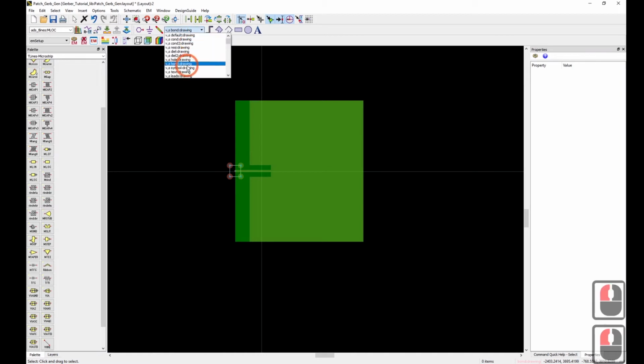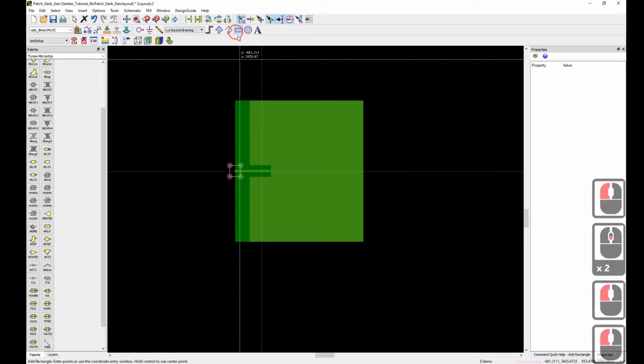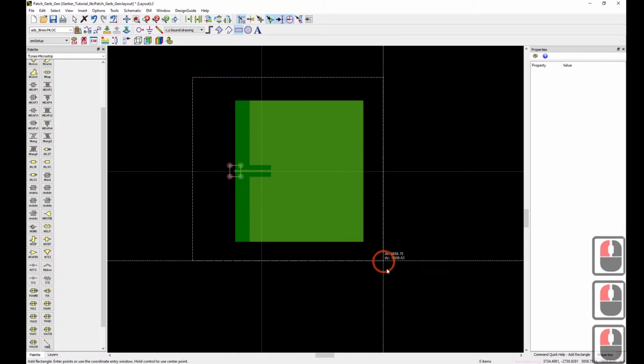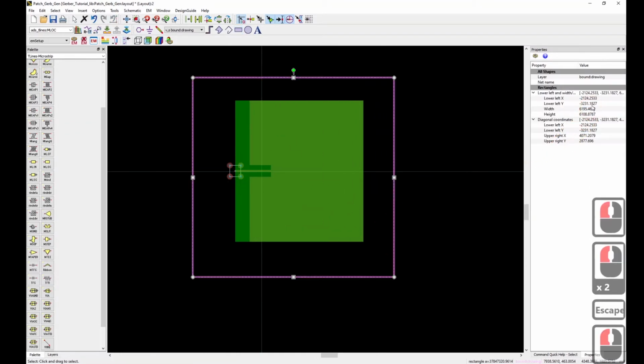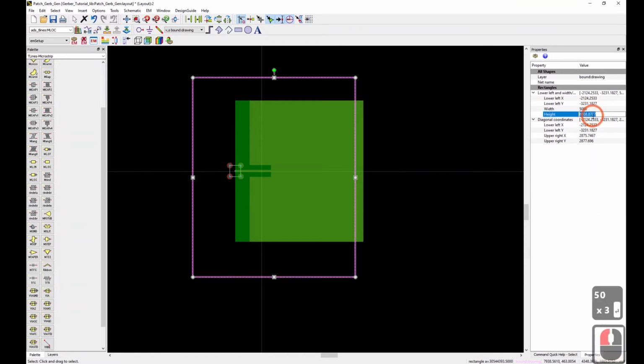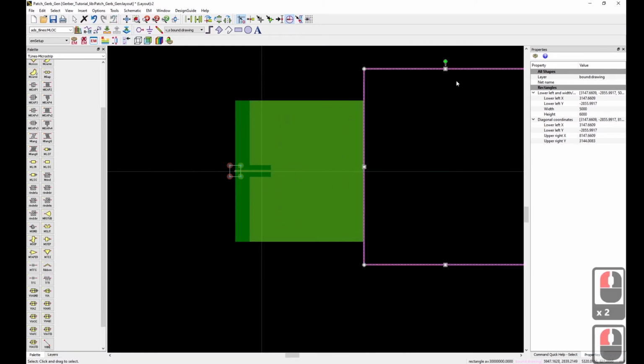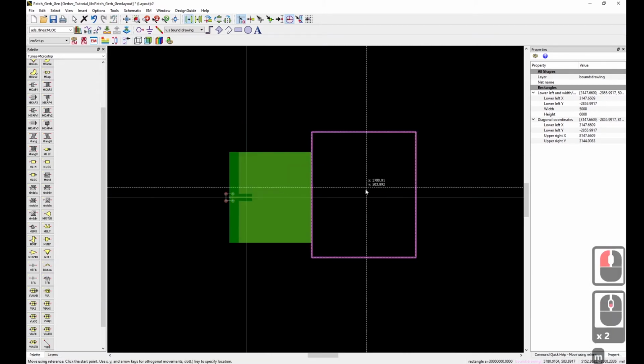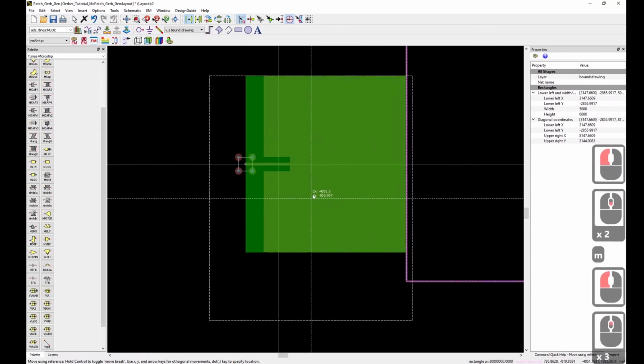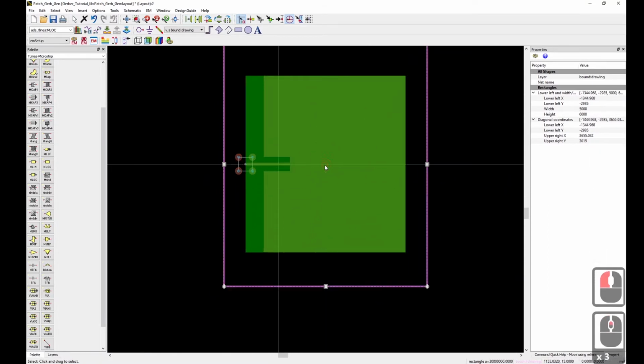So let's create bound. Oops, that's bond. Bound. Let's create a new square here. Let's make it 5 inches, which is 5,000 mil, by 6 inches, 6,000 mil. And let's just turn on center snap mode. Might even be easier if we move this over here for a second. Let's let it find the center. And then over here do the same thing. There it is.